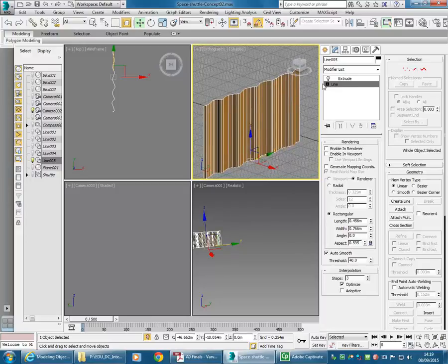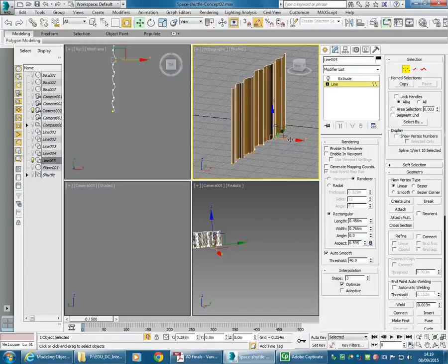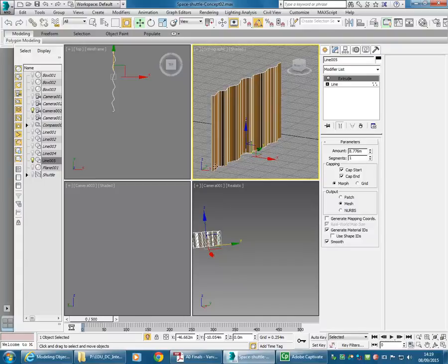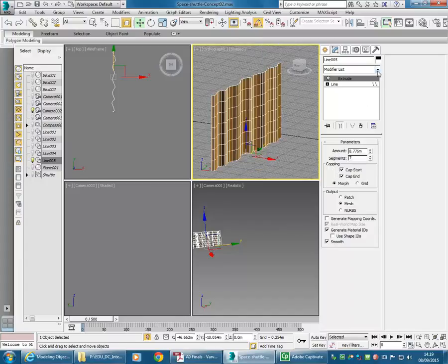And so again, because it's still got the line under the extrude, you can go back to Vertex and lift some of those points off the ground. And just keep adjusting them. Now, you might realise that's just going straight up, and if you want it to be more free-flowing than that, you can maybe add in some more segments. And think about either converting it to an editable poly, and then you can adjust the points individually, or try modifiers.